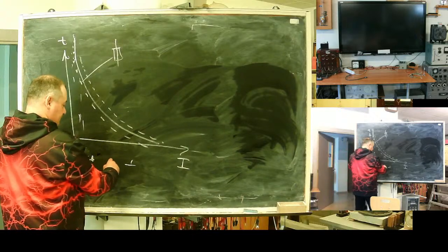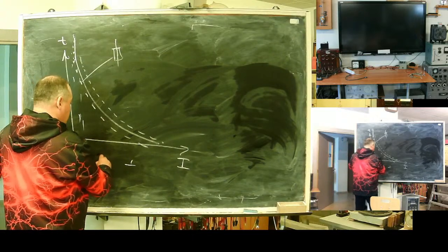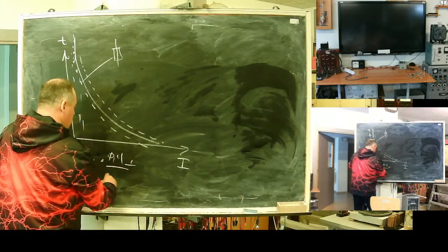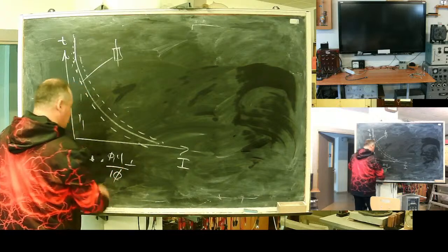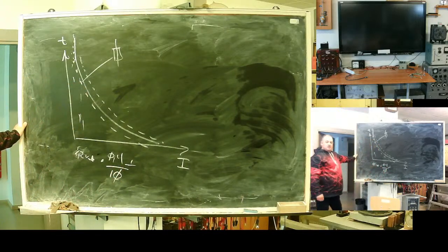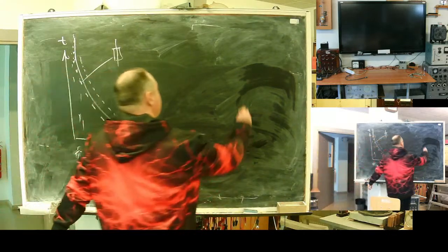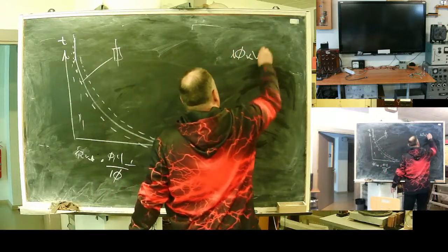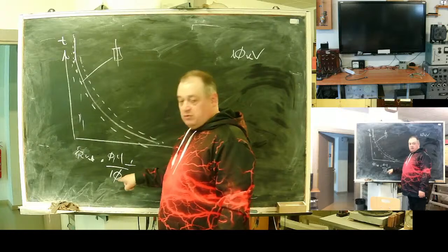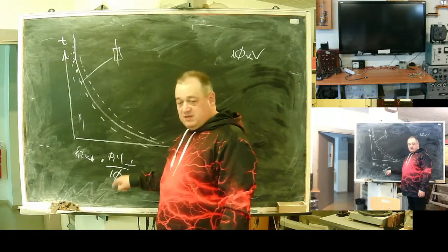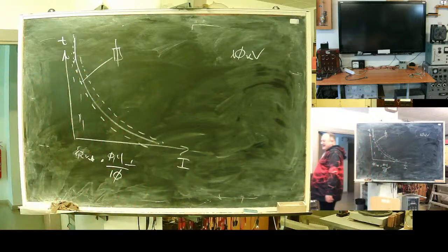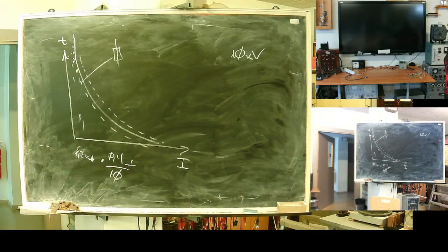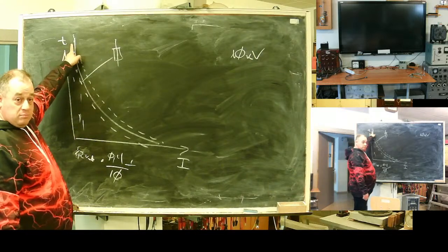1.2 multiplied by 0.4 divided by 10. Why am I doing it? Because I'm calculating on a distribution network. I started from an example where my network is 10 kV. If your network is 11, put 11 here. If your network is 24, put 24 here. We need to reduce the characteristic to one current base or one common current. Okay, here is the characteristic of our fuse.